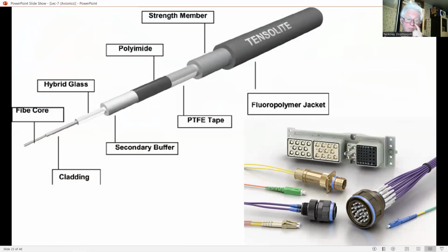The fiber optic cable is also much lighter than the equivalent screened cables it replaces. The weight saving can be significant, and as mentioned a bit earlier, weight saved on equipment installation is geared up by a factor of about 10 on the overall aircraft weight.